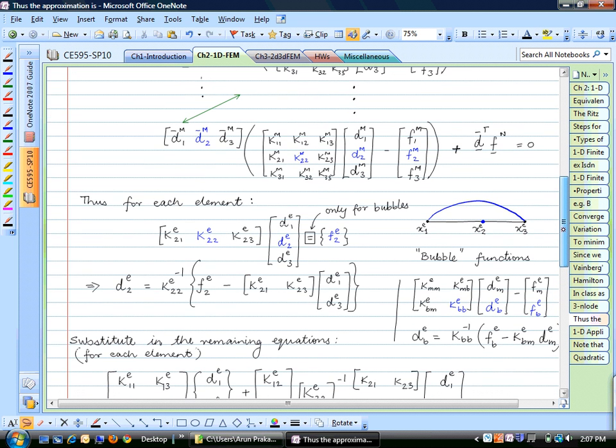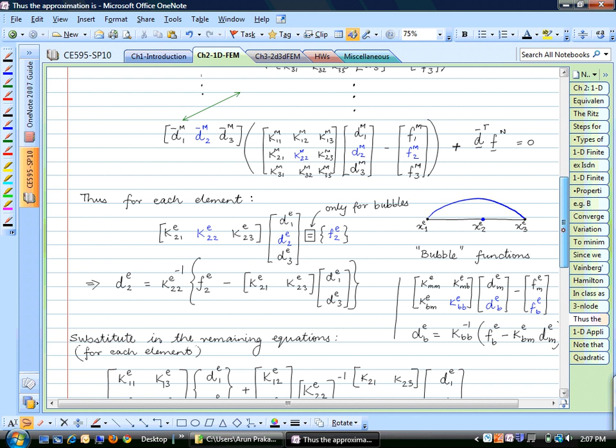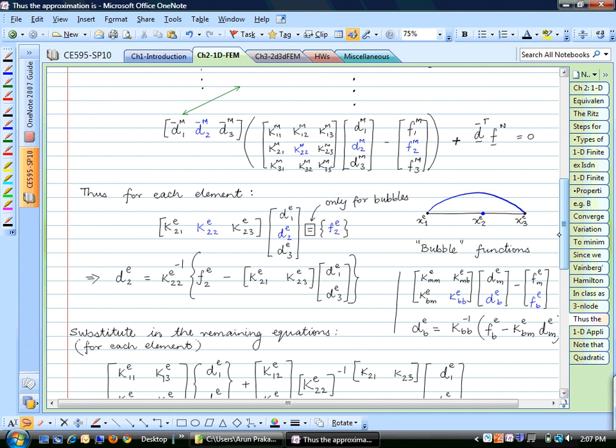So are there any questions on what we just discussed? Yeah. Are there shape functions you would use for higher order? Sure. You can embed this with a trigonometric shape function. You can start out with a 2-node linear shape function and embed that with a cosine or sine function.